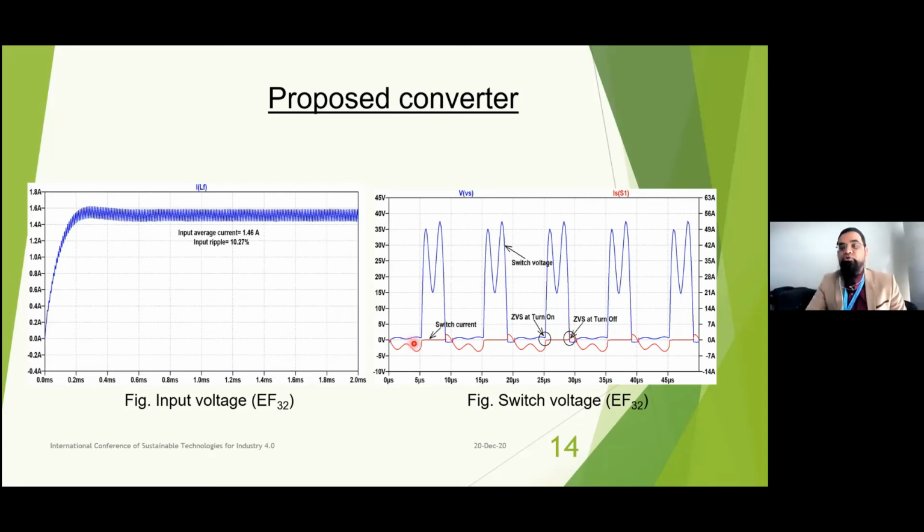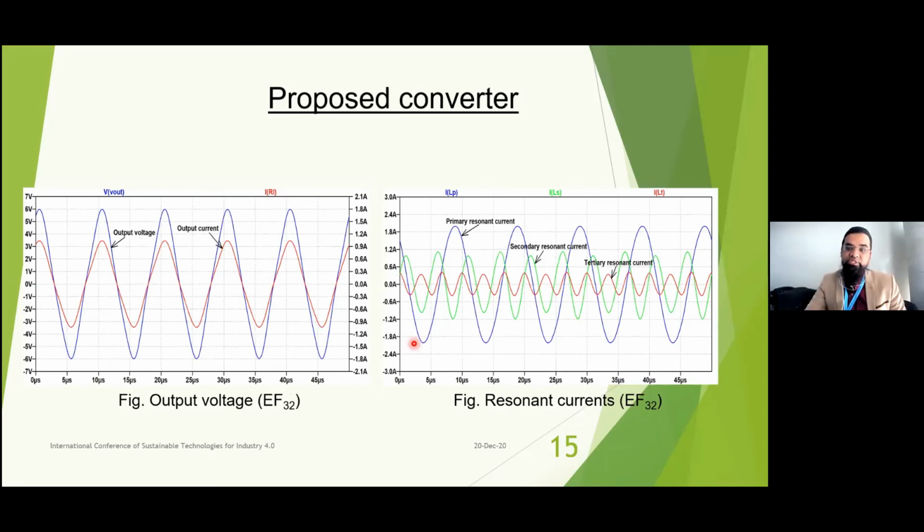This is actually, as you see, a 5-watt device, a 5-watt inverter. According to the industrial standard, if you go above 10 watts, then the IEEE standard needs you to add a power factor correction converter. So this is only a 5-watt inverter. For this application, we have not added any power factor part, and also we have not added any controller circuit here. This is plain, running raw.